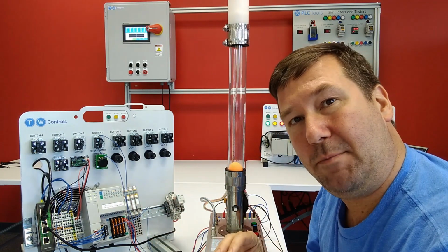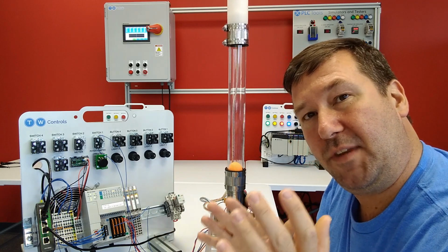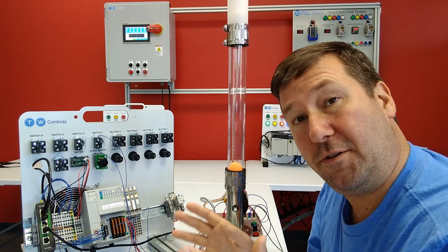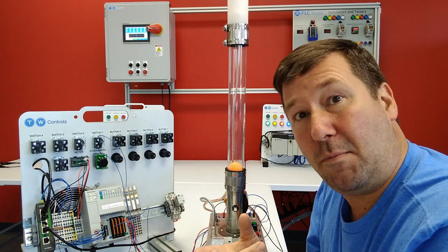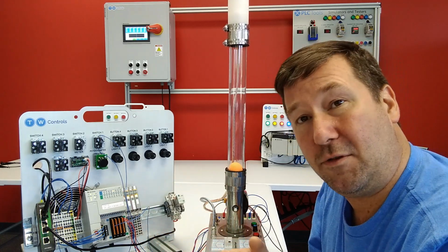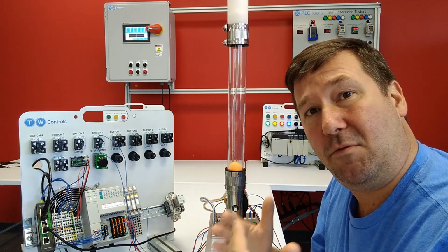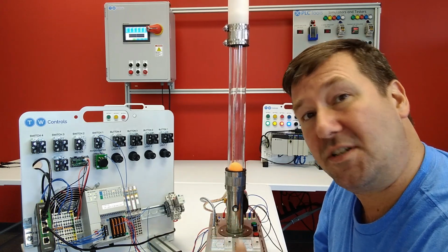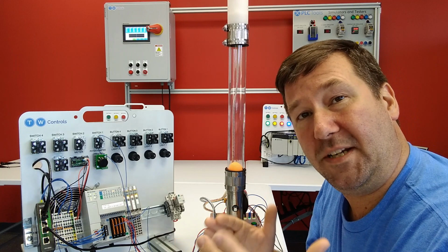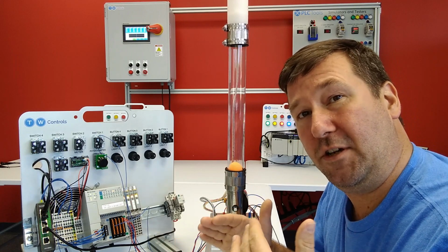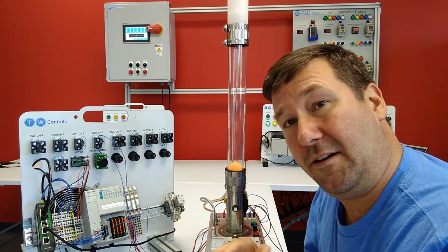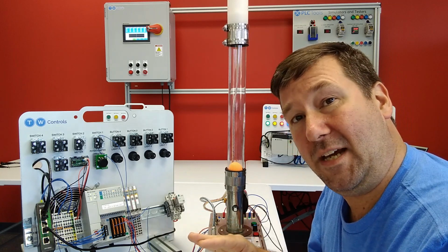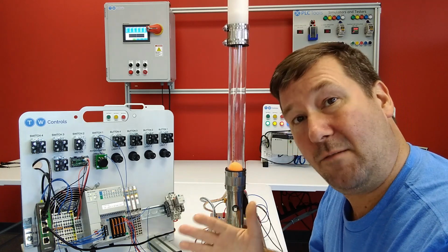but I had a couple people who had issues with the numbers that I had just arbitrarily thrown into my PID. I threw in a 1 for the proportional and a 0.1 for the integral. And the question came up of, well, what if those values don't work to get you going? And yeah, it'll be difficult to walk through this if you don't have at least some starting point. So we're going to do the auto tune without anything done to the PID just to get us somewhere close.